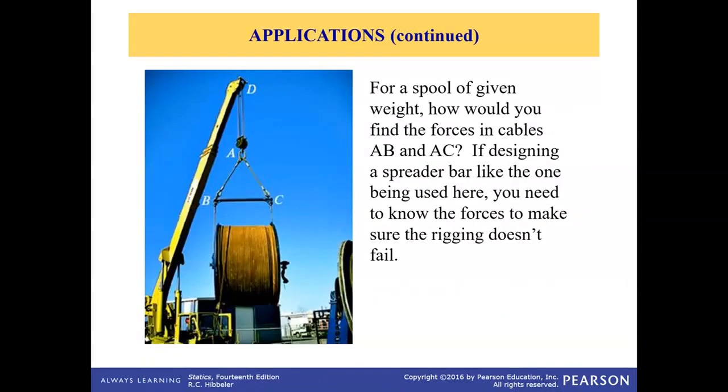For a spool of given weight, how would you find the forces in the cable AB and AC? If designing a spreader bar like the one being used here, you need to know the forces to make sure the ring doesn't fail. And for that, we draw a free body diagram, a simplified diagram made by drawing only hook A and indicating all the forces that are being applied.